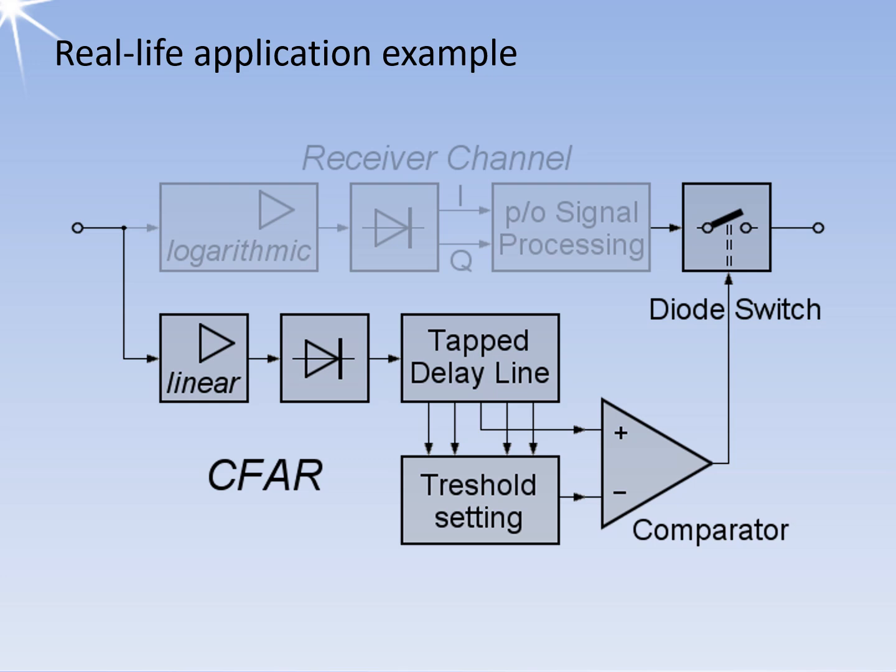The statistical method used to calculate the threshold values is often the subject of scientific work and military research. This has resulted in the development of various methods, for example, trimmed mean CFAR, abbreviated to TM-CFAR, which is a modification of the OS-CFAR. In digital radar signal processing, several CFAR routines can be carried out in parallel, and a selection function only forwards the result with the best signal to interference and noise ratio,